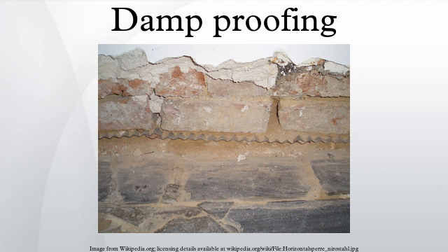Concrete walls and floors. Concrete normally allows moisture to pass through, so a vertical damp-proof barrier is needed. Barriers may be a coating or membrane applied to the exterior of the concrete. The coating may be asphalt, asphalt emulsion, a thinned asphalt called cut-back asphalt, or a rubber polymer. Membranes are rubberized asphalt or EPDM rubber. Rubberized products perform better because concrete sometimes develops cracks and the barrier does not crack with the concrete.